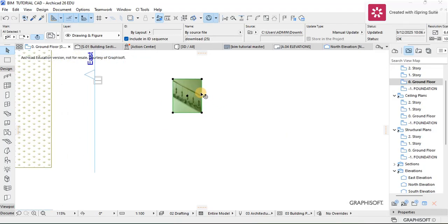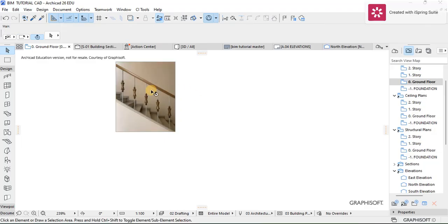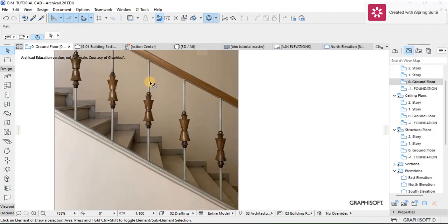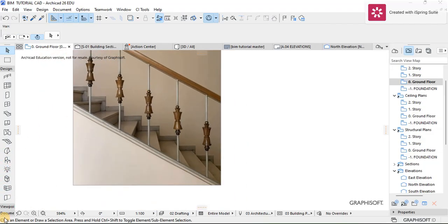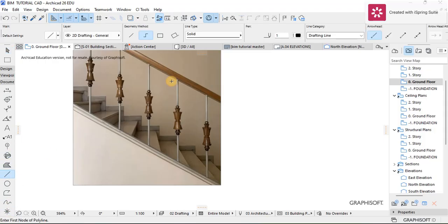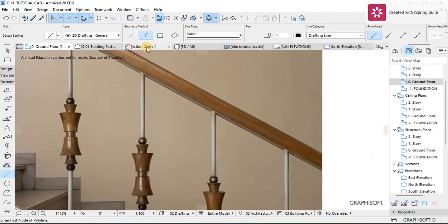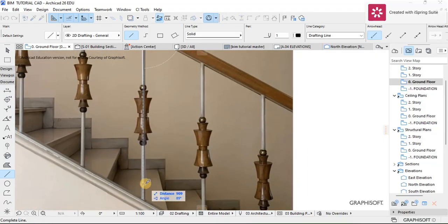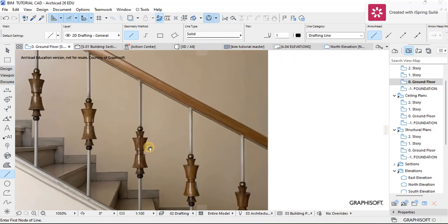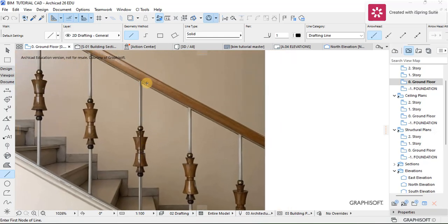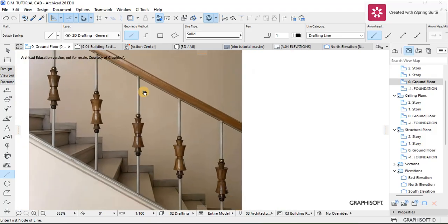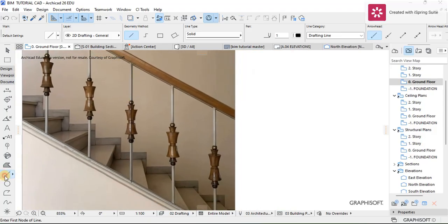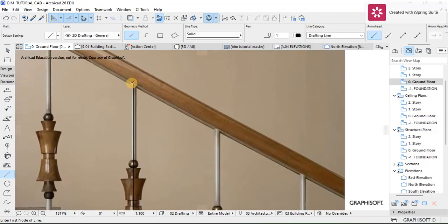Then I'm going to draw the outline for my railing. What you want to take note of is that you are going to cut this thing in half. I'm going to slice this area here, half like this, and I'm just going to draw this part of it, because I'm going to be using a tool that will enable me to revolve it and finish the whole thing.